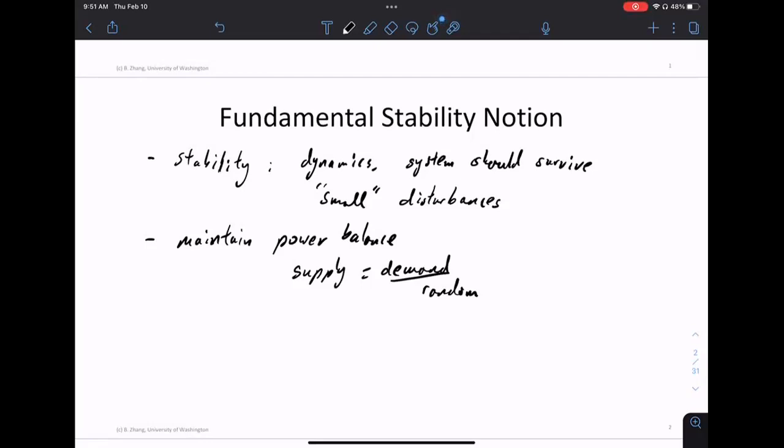So that's the interesting thing about power system control that's different from a lot of other control problems. You don't know the target. Nobody ever tells you what the demand is. This demand changes stochastically, randomly all the time, and you're asked to track it. So the way we do this tracking is the following. As generators, you don't know the demand. So when the demand first changes, you don't know it, and you still supply the same amount of power. So a changing demand